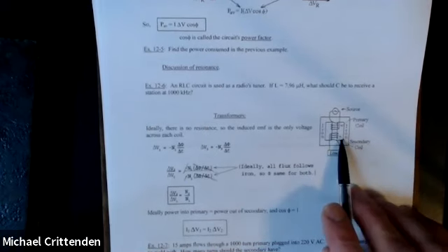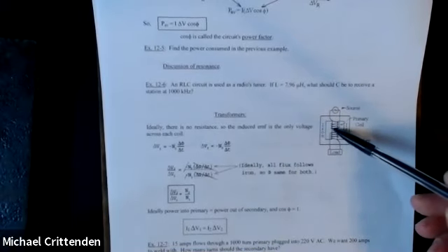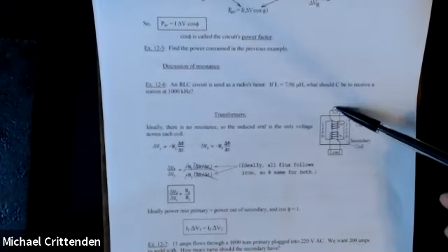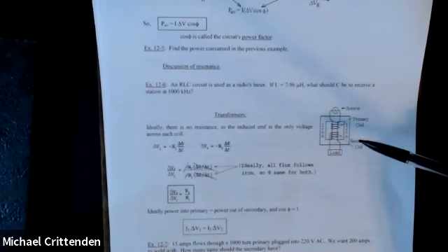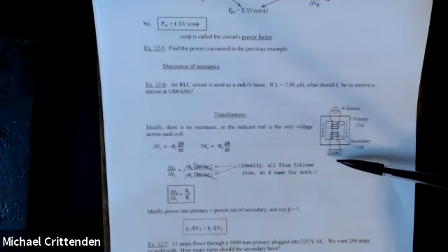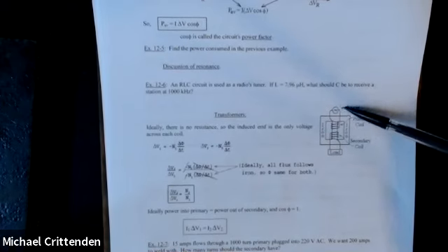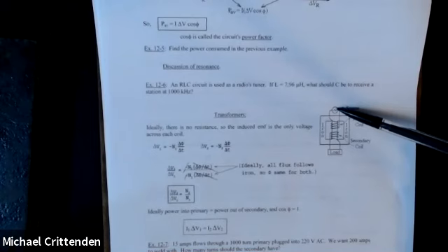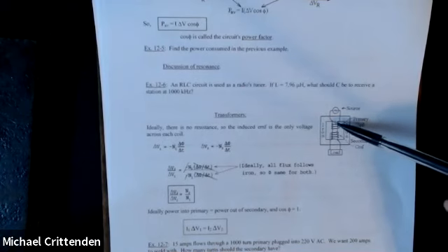So here we have a typical geometry. You have the primary coil, which is the coil that you put electrical energy into. So for example, if this is the transformer in your cell phone charger, you have to step the voltage down to something like 5 or 6 volts, something appropriate to charge your battery with, and you're plugging it into a 120 volt household outlet. So this would be the 120 volt outlet that you're plugging the cell phone charger into. And the current goes through these primary windings and creates a magnetic field. The magnetic field lines follow the iron.